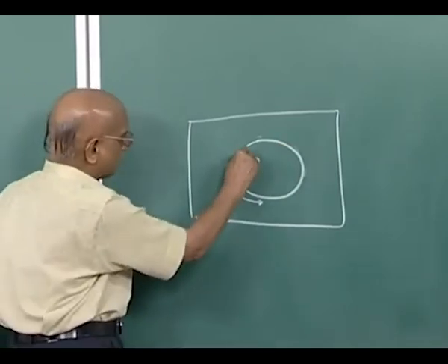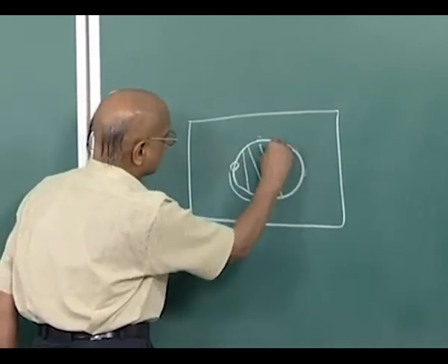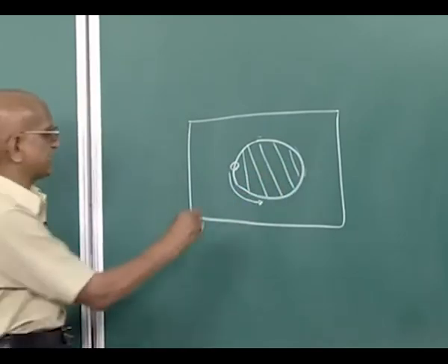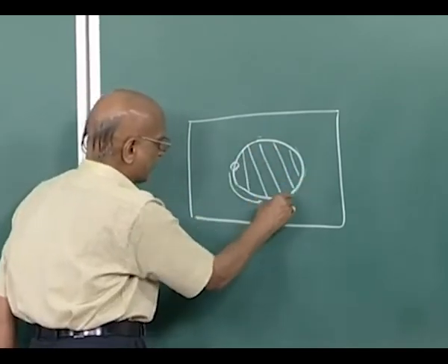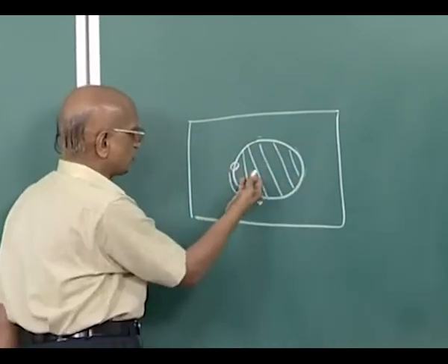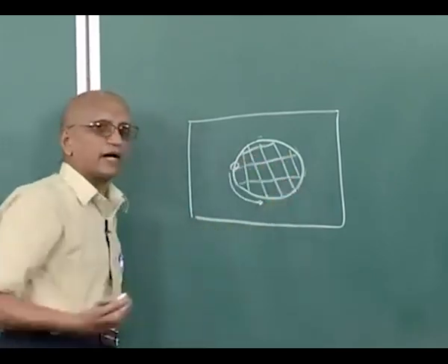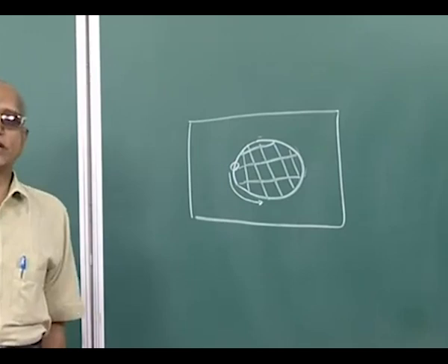This is the whole of the material that is to be removed. So instead of cutting or melting and vaporizing all of this material, you can perform the trepanning operation. When you perform the trepanning operation, the shaded portion will come out as a solid piece.